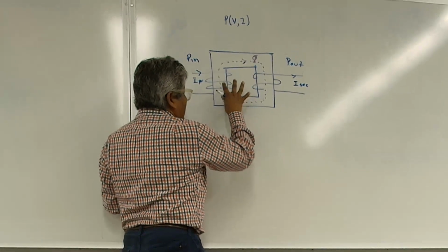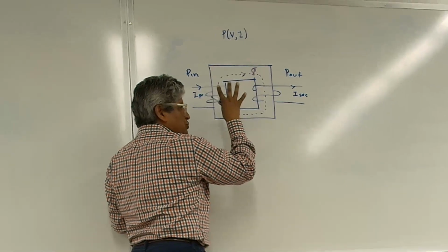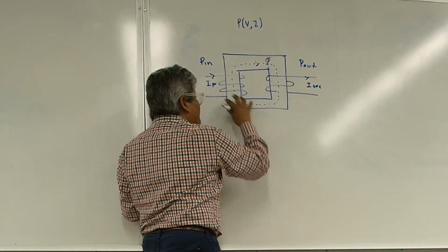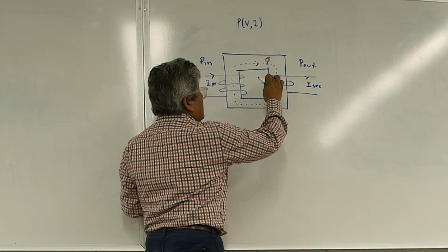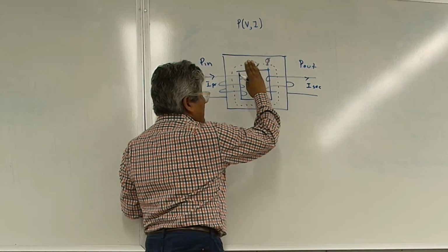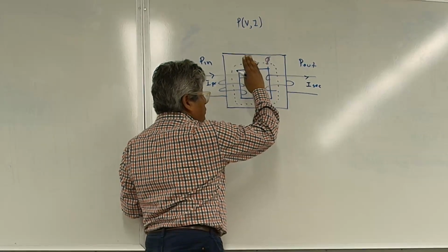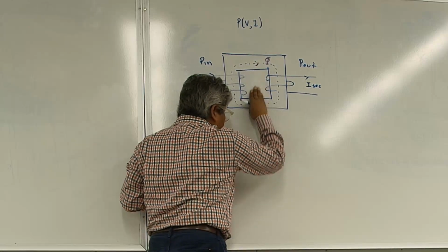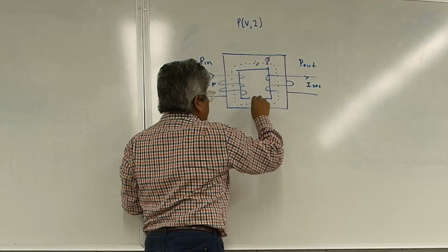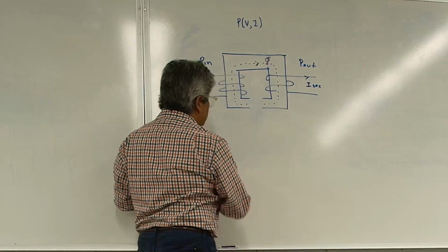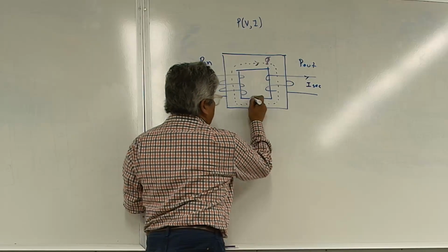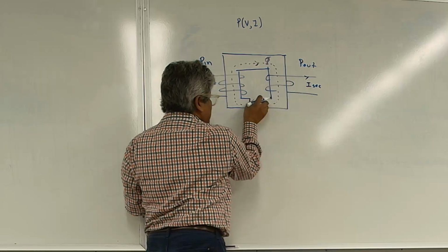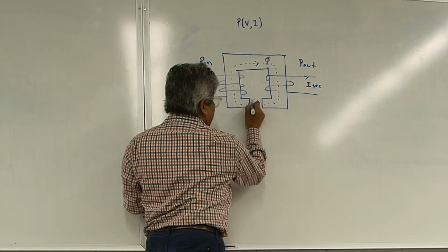So the reason why transformers in comparison to rotating machines are so much more efficient is because all the flux is confined in the core. If you have a rotating machine or a motor, generator, basically what you're doing is you're cutting the core, right? You can think of it this way. You have a rotor, this winding goes here, but you have air.